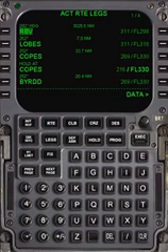The FMS also sends the flight plan information for display on the navigation display (ND) of the flight deck instruments Electronic Flight Instrument System (EFIS). The flight plan generally appears as a magenta line, with other airports, radio aids and waypoints displayed.